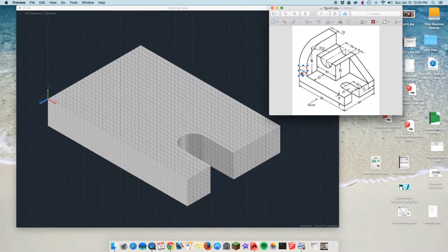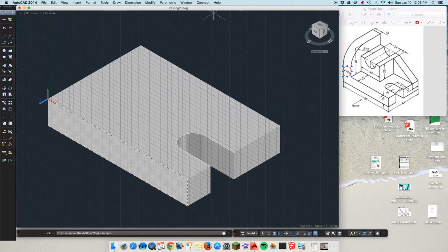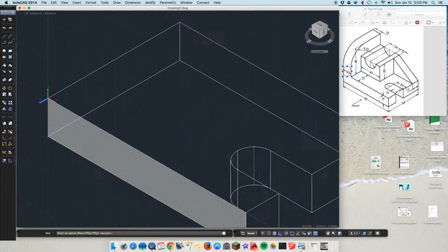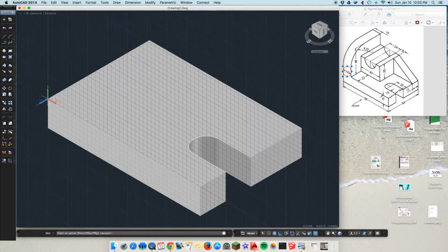We're going to use something we haven't used since the very first project in pre-engineering, which is absolute coordinates. The program translates everything into X, Y, and Z. Since we've moved the UCS, this place right here is where 0, 0, 0 is. We've kind of retold it that. Now if you look at your screen, it actually says negative 96, 0, 0, but we're going to try this and see if this works.